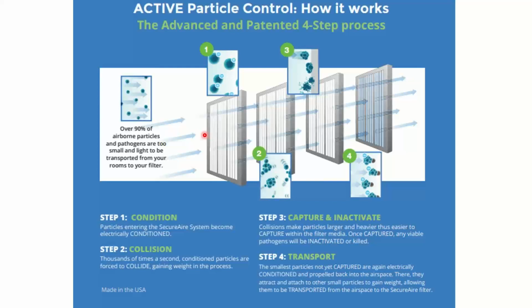So Secure Air does that. It's all in one box, if you will, and the whole thing gets rated as the filter. So the media density has the pressure drop feel of a Merv 12, but the rating ends up being a Merv 15, which is kind of cool.